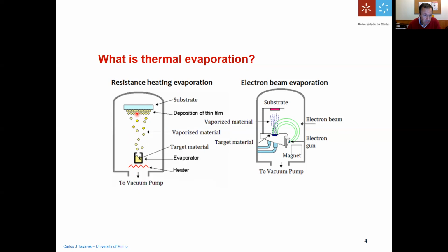So you will need to evacuate this chamber so that the mean free path of these particles will be large enough, comparable to the distance from the crucible to the target surface, in order that the particles may reach the substrate with sufficient energy so they can nucleate. They can behave as atoms which can run all over the substrate to find the best nucleation sites possible to nucleate and grow the thin film, according to the thin film growth mechanism that I showed you in the first chapter.